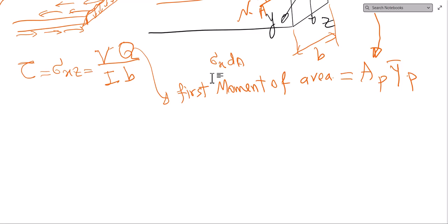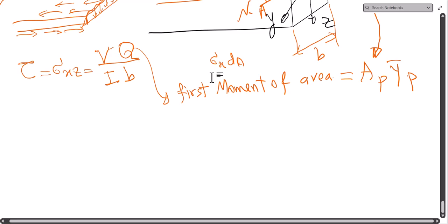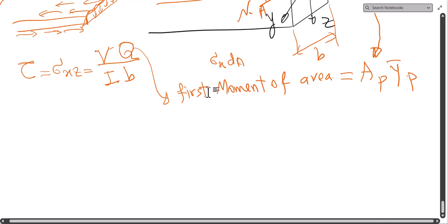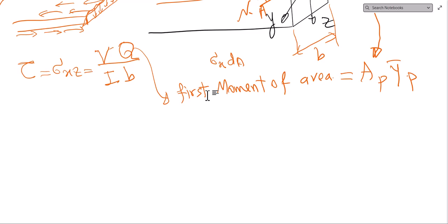At the end of the series, I will go through an example, or maybe a couple of examples, which are descriptive for all of the theories that I'm going to cover. To give you some hint, besides Euler-Bernoulli, I will cover Timoshenko beam theory, and Reddy's beam theory, a third order treatment of the displacement, and it recovers fully the shear.